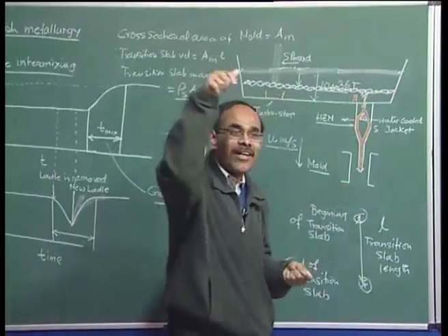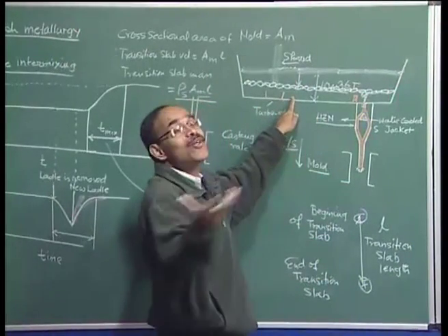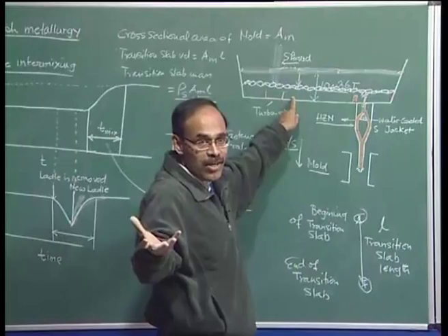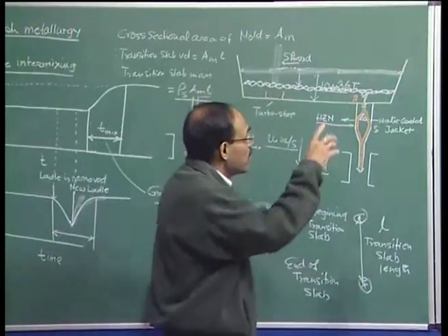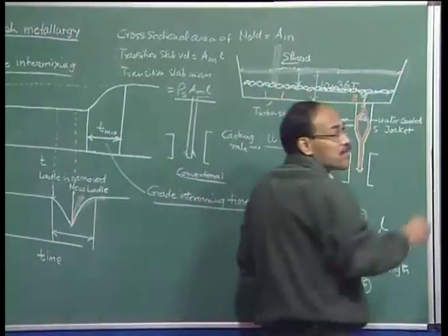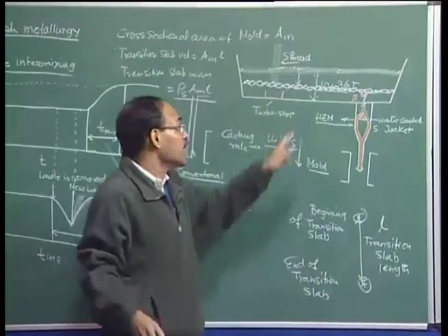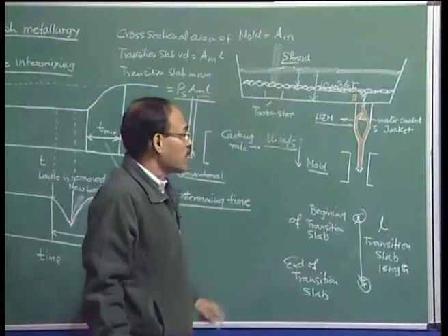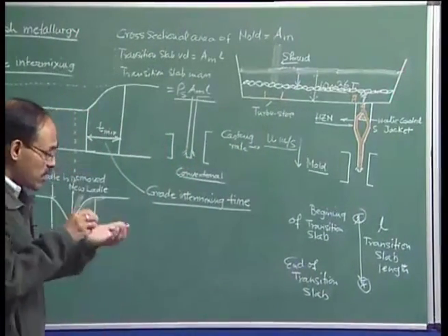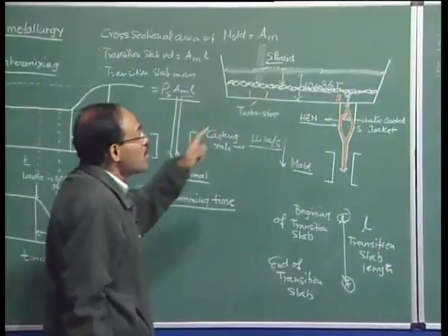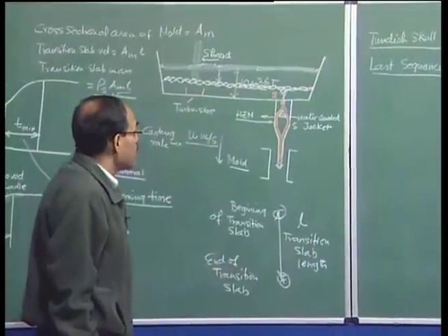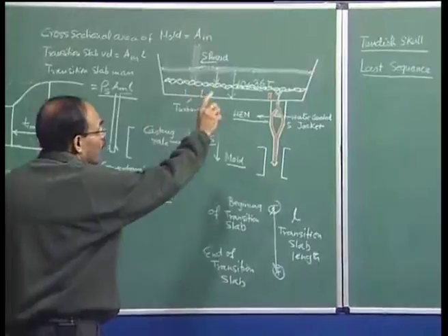So much material they have charged into the tundish, and how much billet or bloom they have formed, and the amount of tundish skull really gives the plant an idea of the yield in the continuous casting tundish system itself.